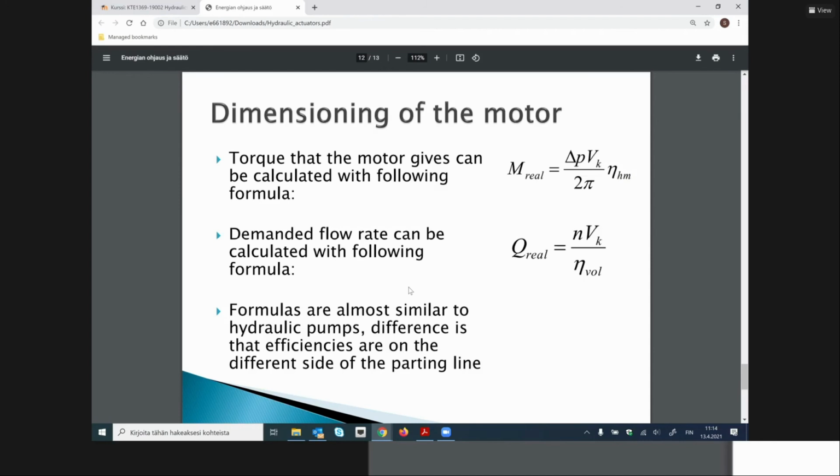But of course, if you want to make the cylinder move faster, then you need to press more gas so that the spinning speed of the pump becomes higher, and the flow rate that it generates is also higher. So it might be that in idle it moves very, very slowly, and this is normal.